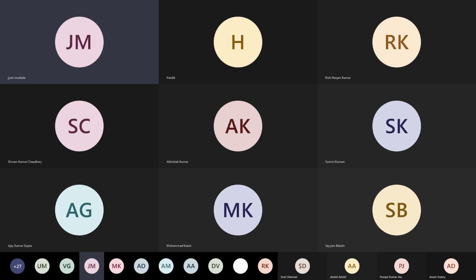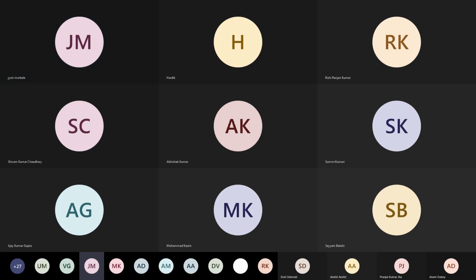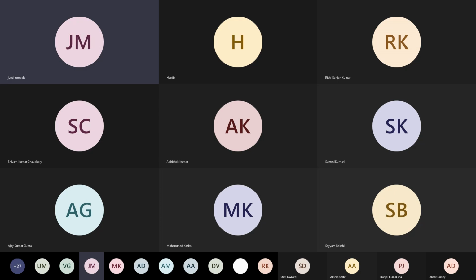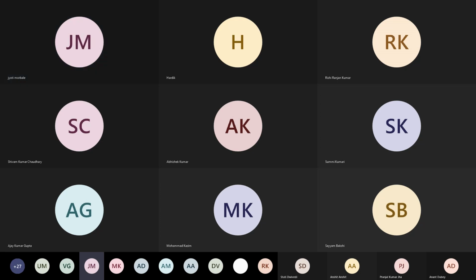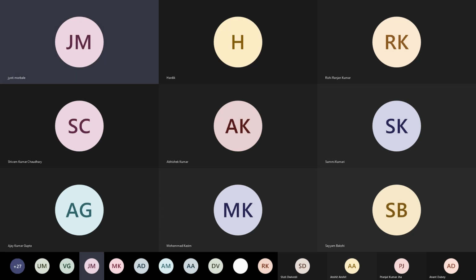When these minority charge carriers move or accelerate through the structure, they break some covalent bonds, and after breaking the covalent bonds, new carriers are generated. Again, these newly generated carriers get sufficient energy to break more covalent bonds, and in this way a chain reaction is created, and a large number of free electrons are generated that gives rise to the high reverse current. This breakdown is called avalanche breakdown.